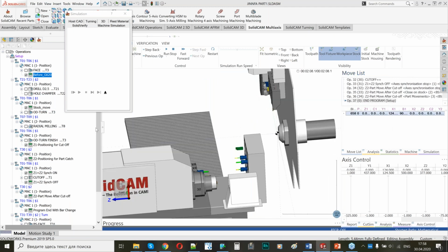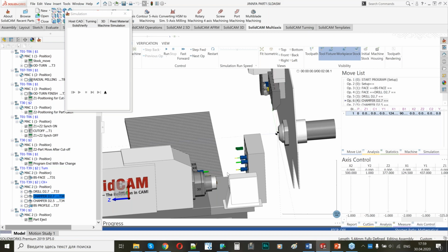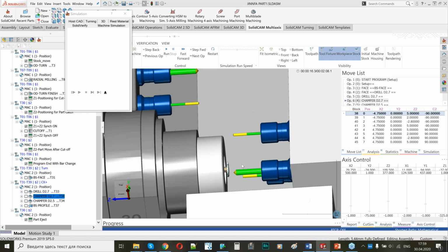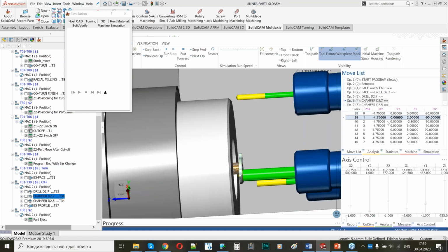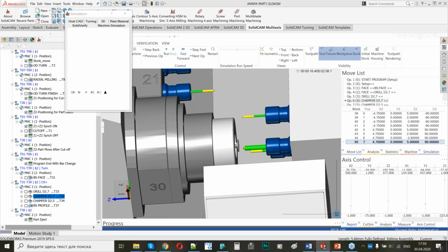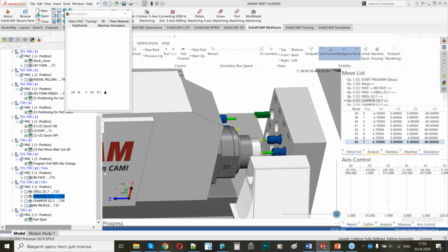That's all. I can also show separately what's going on with the back spindle. For example, it is nice to check my polar movement for the back spindle here. What I have here. Yes, my part rotated with the Z-axis, and the tool holder didn't move in the Y-axis.